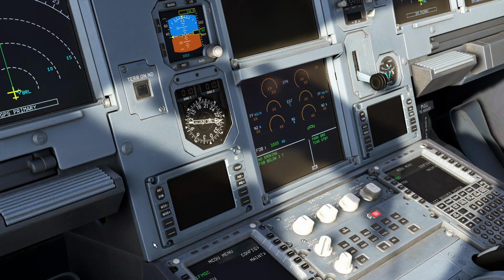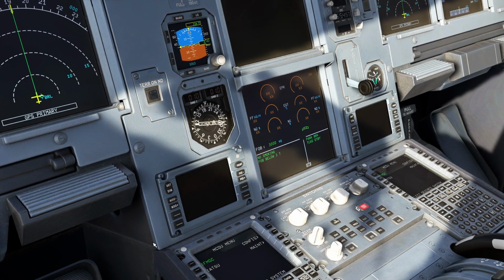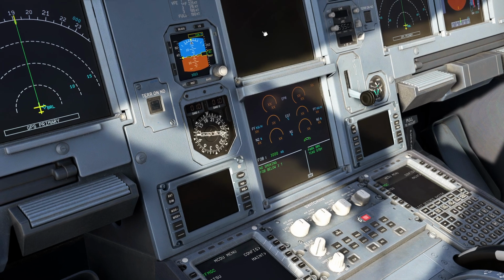The engine warning page automatically replaces the system status page on the lower ECAM DU. From the upper side, the image of engine warning display jumps into the system display, which is located in the lower part of the ECAM display section. The flight crew can display the system status page, which is previously presented here on system display, using the ECAM ND transfer switch,